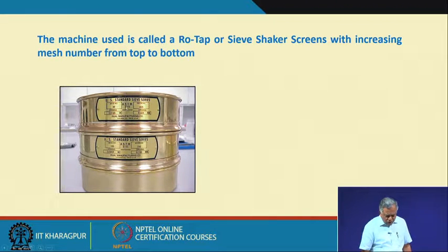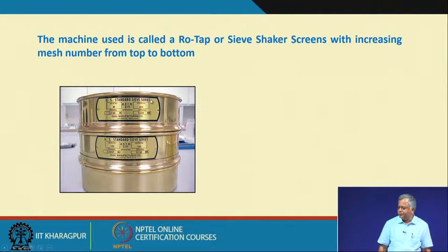But if you look closely, there is some information given on the sieves also. It is written US standard sieve series, sorry, it is not BS, it is US standard sieve series. So, when you are using a US standard sieve series, your subsequent sieves have to be from the US standard, possibly from the same manufacturer.